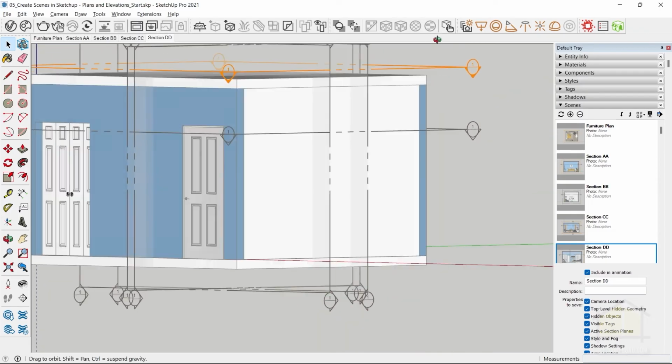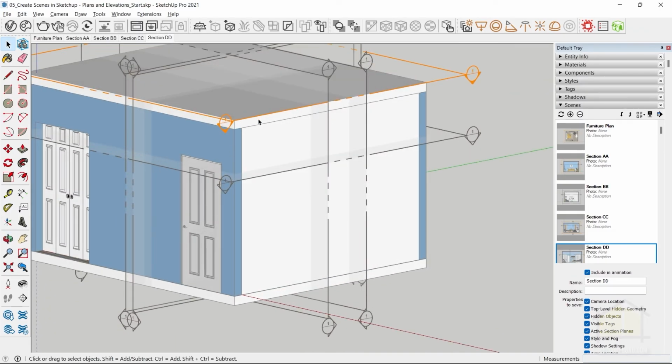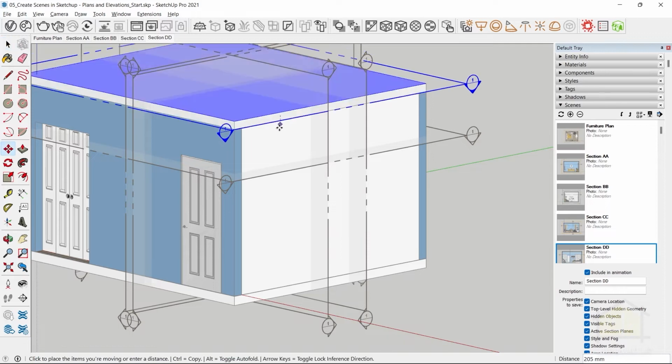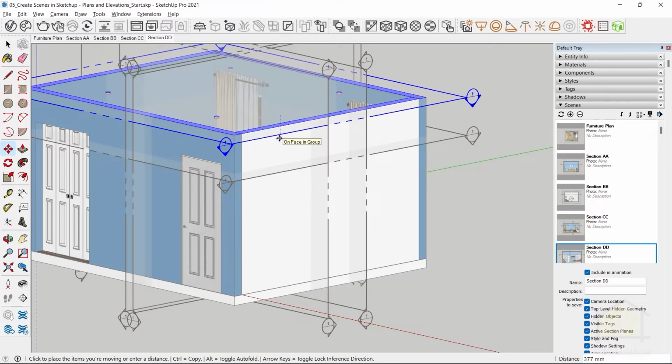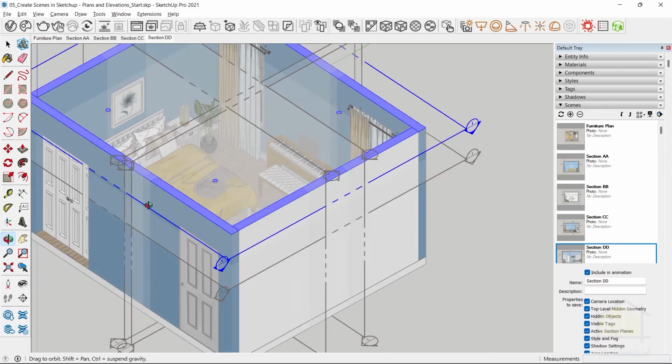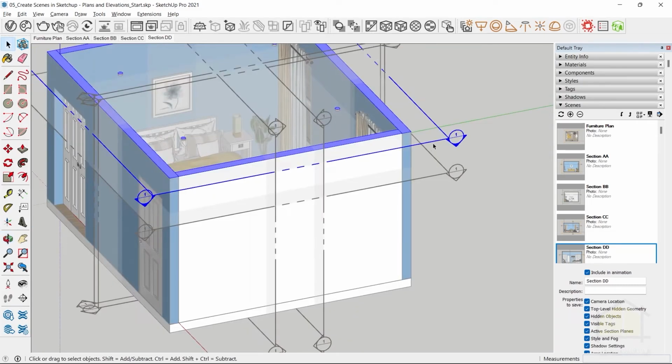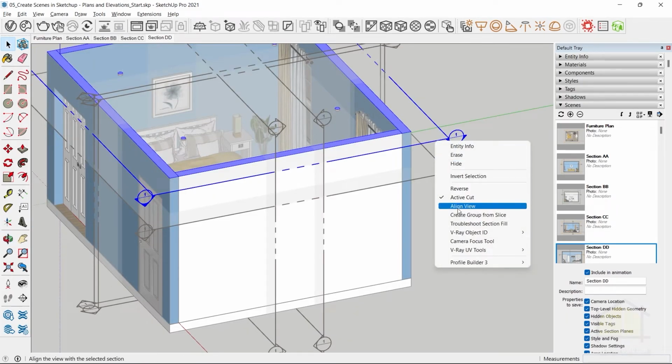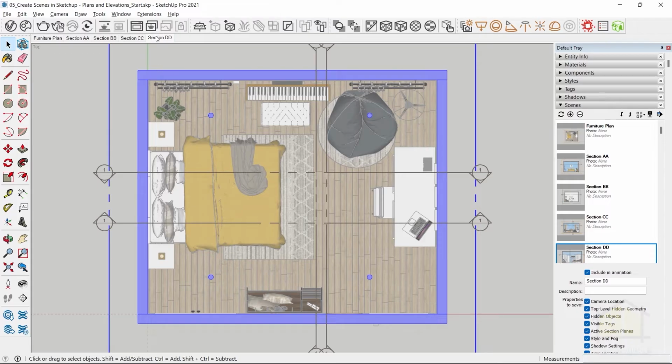So I've activated the section, but it's not really cutting anything. So I'll have to move it down a bit. So select the section, move it down. So now you can see these 4 lights here. That's all I need for this room. And then I need to go to the top view as well. So you can right click, click on align view. And then I can add my RCP plan. So right click, rename this, call this RCP plan.